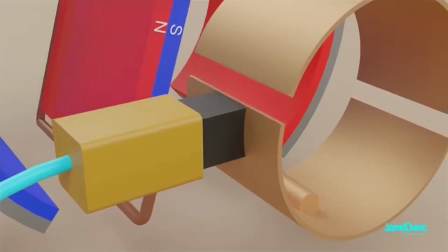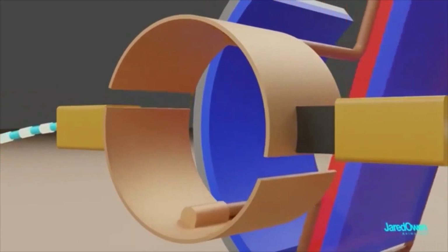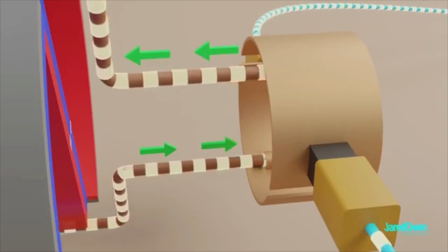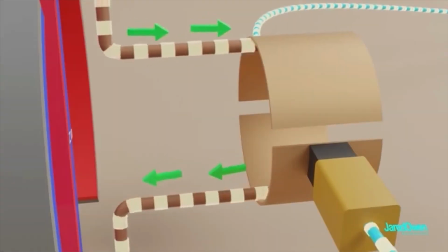An armature can only make half a rotation because the sides of the armature get reversed, and so do the magnetic forces acting on them. To continue the rotation, we need to reverse the direction of the current after each half rotation, so a split ring is used to flip the current.